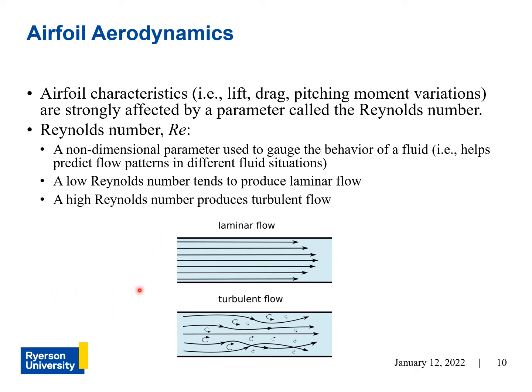At those two Reynolds numbers, the airfoil will effectively behave as if it was a different airfoil, because of the quality of the flow around the airfoil. So that's why the Reynolds number is important to know.